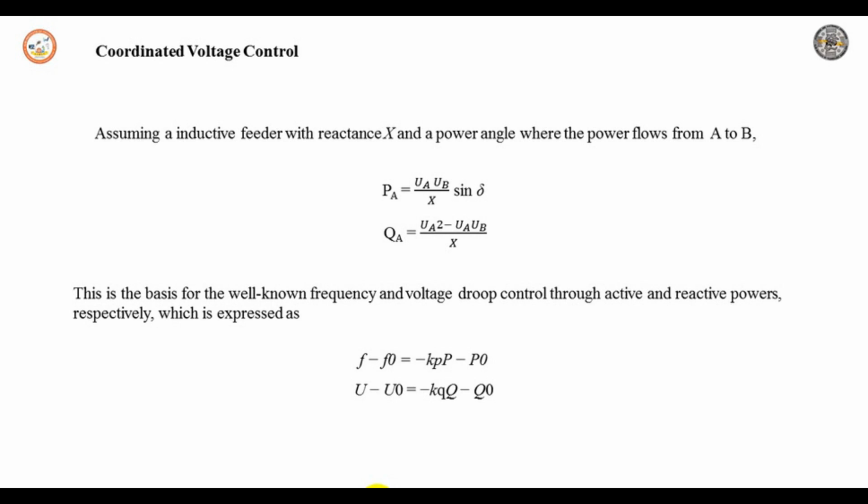So voltage control coordination is essential in transmission and distribution grids in order to maintain the voltage within acceptable limits, and at the same time to prevent counteracting operation of individual active devices and maintain stability. Generally, having a parallel device with the same assigned function is also beneficial from an operational point of view regarding power sharing and reliability, while maintaining the n-1 criteria. So the droop scheme is a classic way of coordinating different active devices without the need of any communication signal between them.